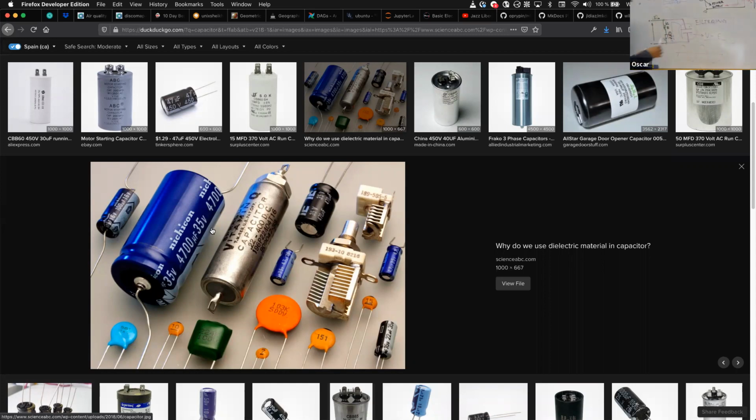If you make this exercise with one of the capacitors, where is the capacitor in that drawing? This is the capacitor, and normally they are represented like this or like this. So this is ceramic because there's no polarity. These are electrolytic because this is the negative side. These have polarity.